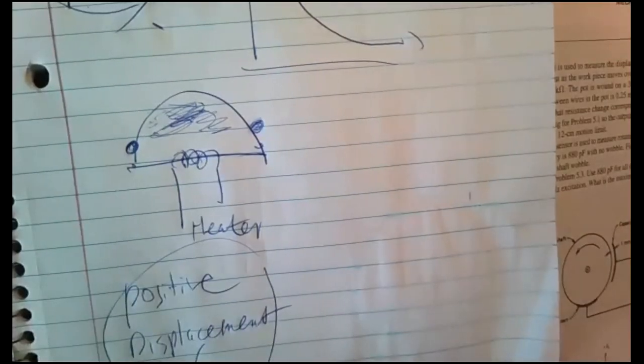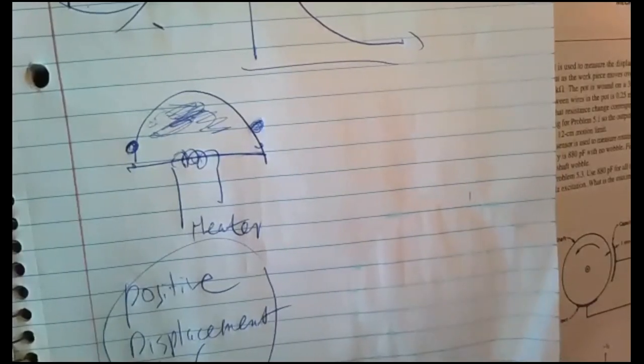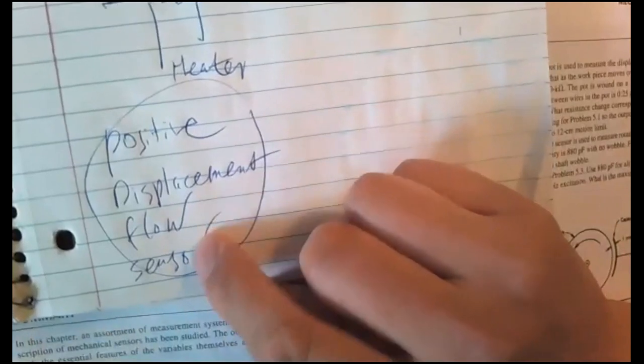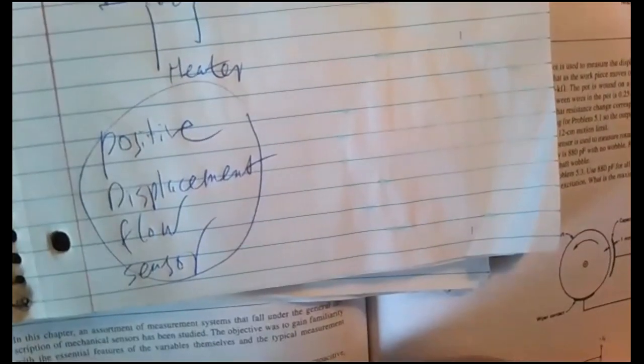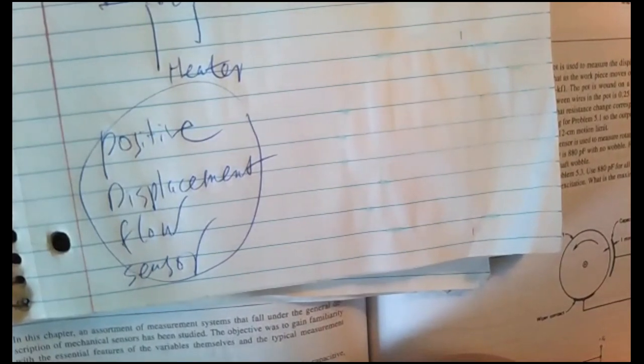Yes. But it's not necessarily measuring the rate of flow, because it's measuring volume. Yeah. Sometimes it can take longer, depending on the flow rate. It can take longer to get that 500 gallons, or it could be faster depending on what the pressure is. Yes, that sensor may be a positive displacement flow sensor. You're pumping through a set of mechanical gears, and every rotation, a fixed amount of volume is pushed through.